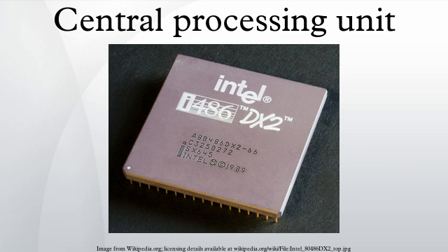To gain some of the advantages afforded by both lower and higher bit lengths, many CPUs are designed with different bit widths for different portions of the device. For example, the IBM System/370 used a CPU that was primarily 32-bit, but it used 128-bit precision inside its floating point units to facilitate greater accuracy and range in floating point numbers. Many later CPU designs use similar mixed bit width, especially when the processor is meant for general-purpose usage where a reasonable balance of integer and floating point capability is required.